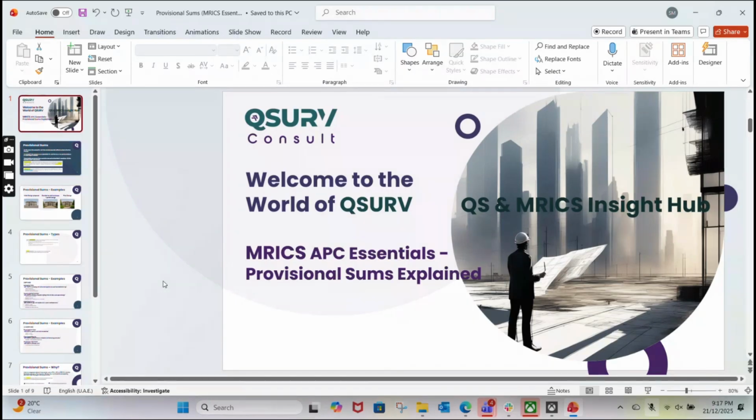And at least hereafter, in the preambles, you have to mention that the contractor is obligated to submit the BOQ breakdown for each and every item, including material, labor, prelims, OHP, risk. Put it in the preambles, somewhere like question number 12 or 13.